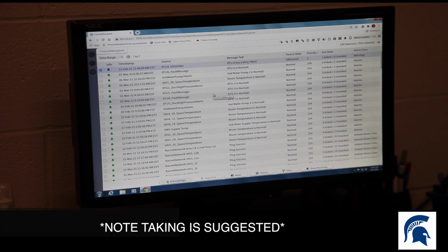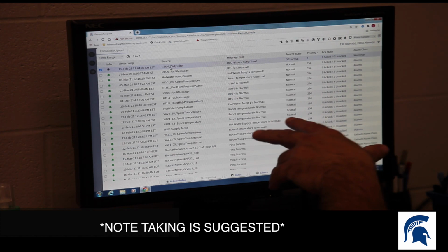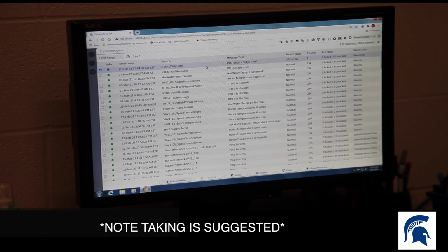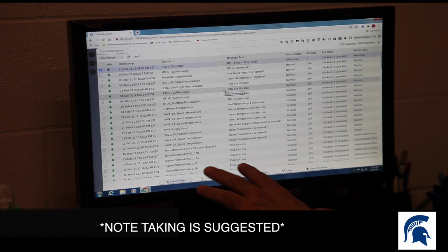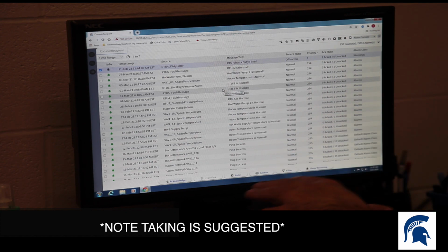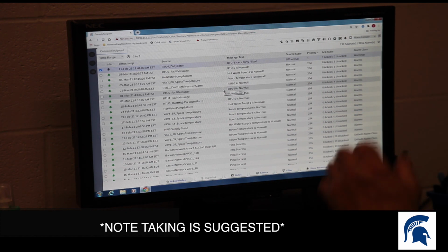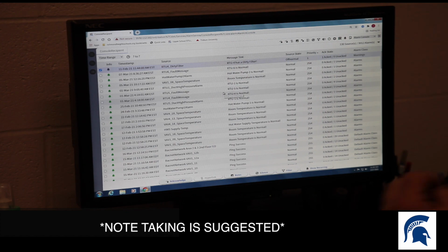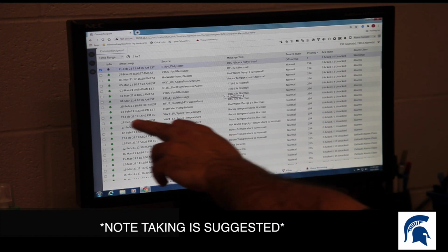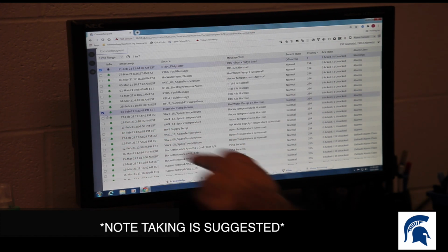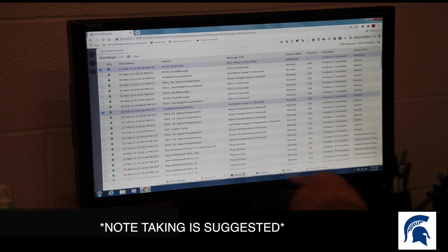So if you go back to RTU4, we'll see if we can reset that. Okay, and when I get an alarm on this and it's beeping, it was driving me crazy. How do I stop this beeping? If you hit the X, you can then get the silence. Yeah, that should make it stop beeping. So we can get out of alarms.